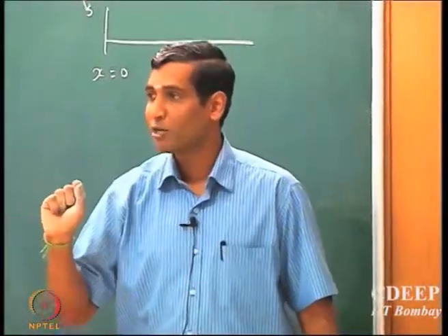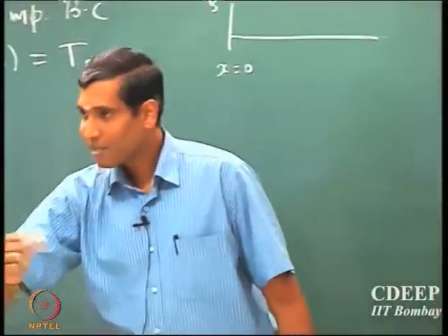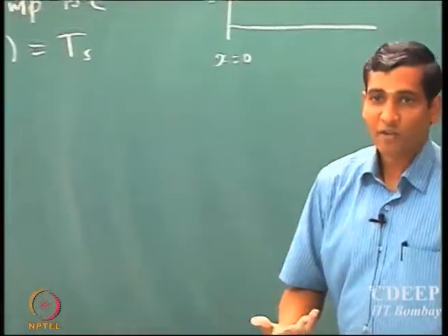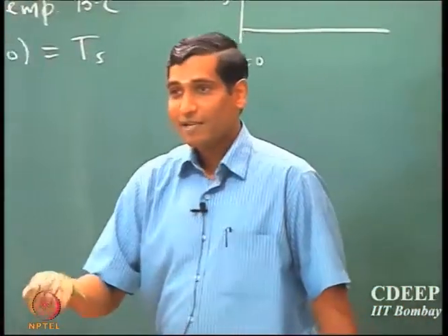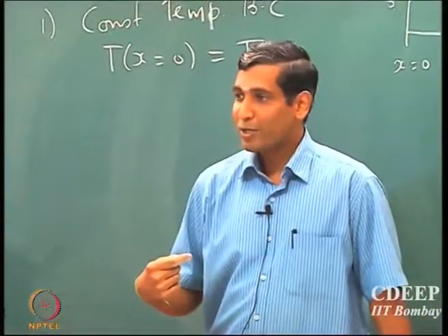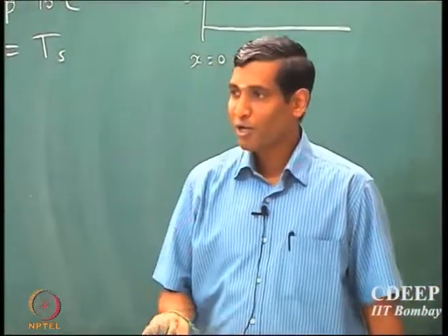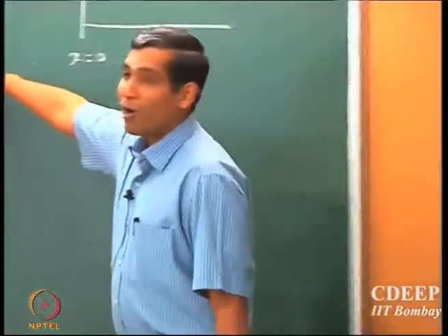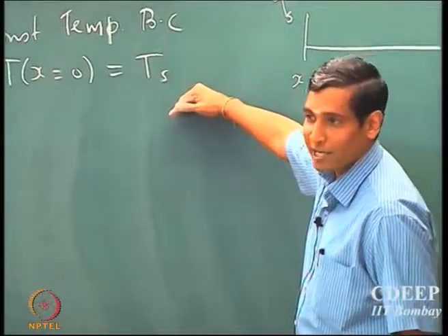Note that it is not the temperature of the water that it maintains, it is actually the temperature of the heating coil. So, if you are trying to write a model of this system to find the temperature distribution of water, then one of the boundaries, where the water is exposed to the coil, will be maintained at a certain constant temperature. So, a constant temperature boundary condition is what you should use at that time. Okay.